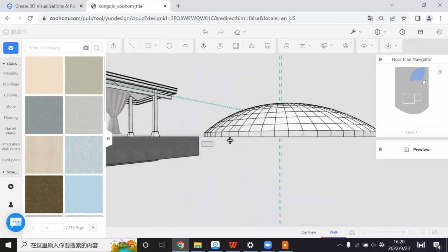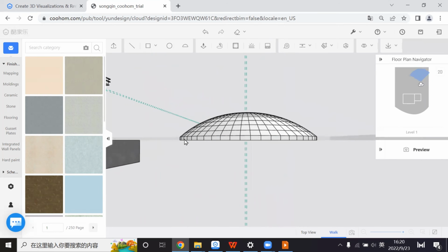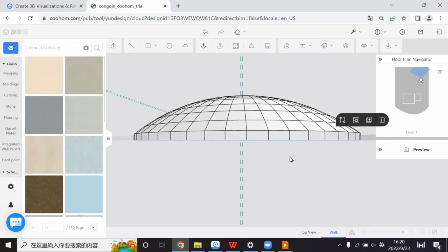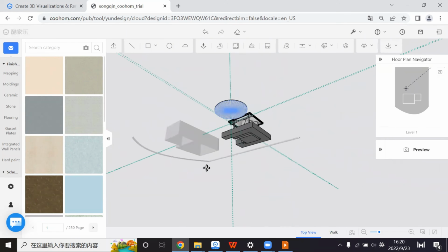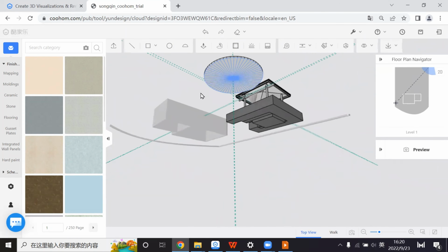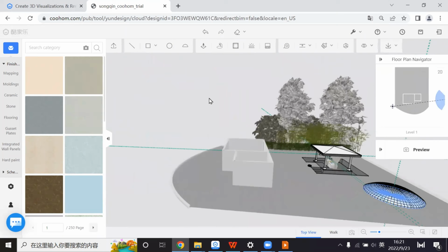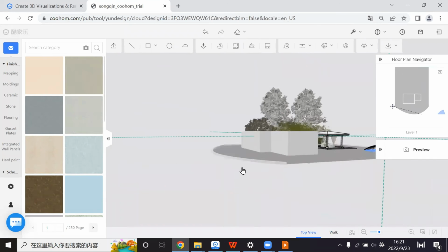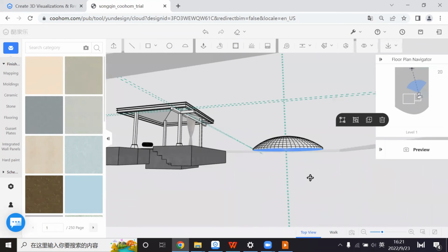And if you can't see clearly, try to select the minimum surface. For example, here I try to select the minimum size, and check under the 0 height. You can see now I select this one. Don't select above or in other directions or holding down the shift button one by one. That's too annoying. You just need to use the 0 height.